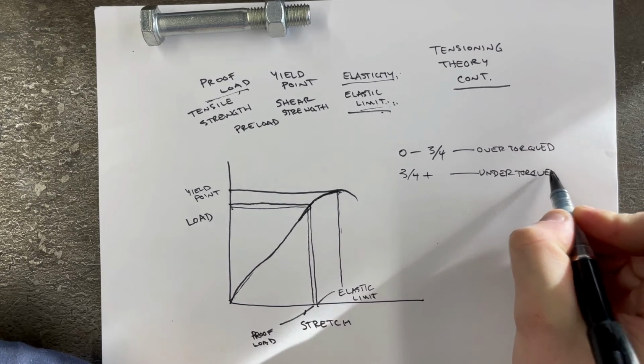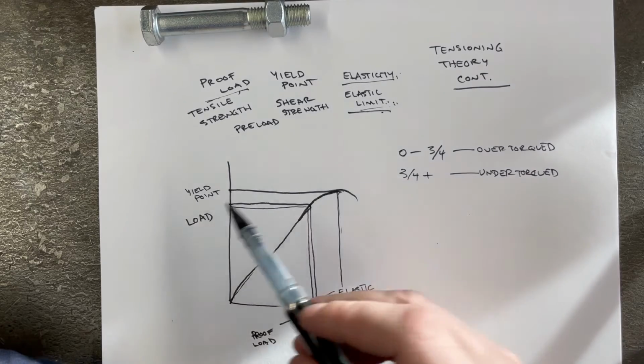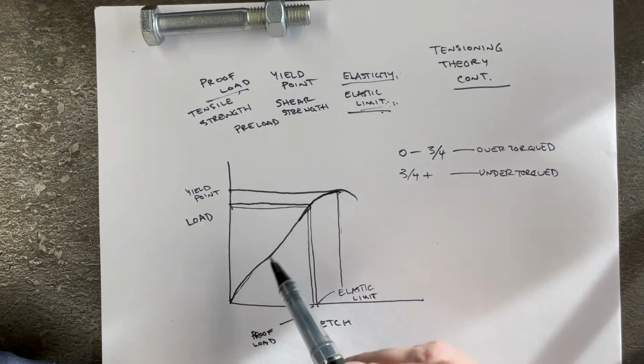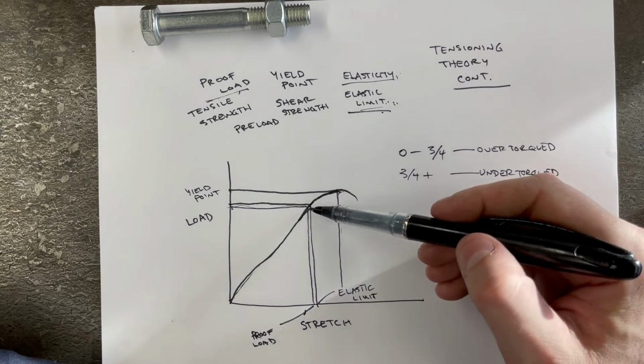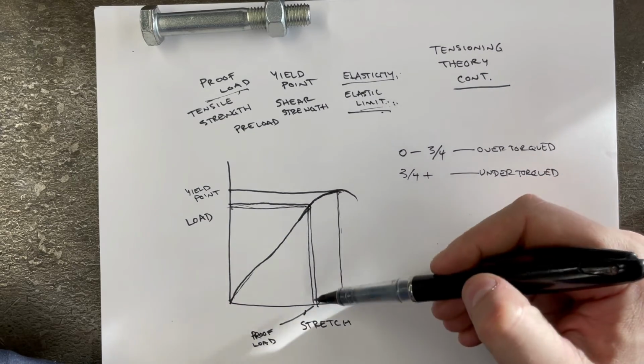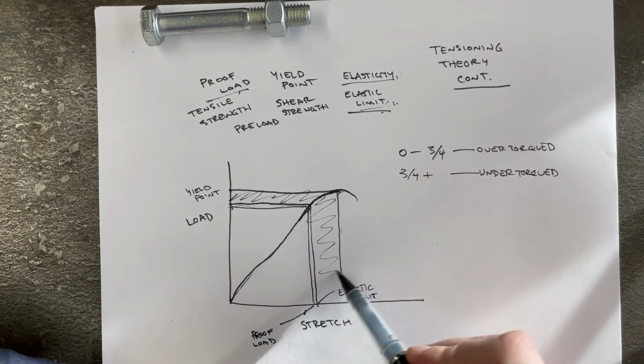So that's why, if you were just to do it by hand. So that's why it's really important when you're dealing with fasteners to keep in mind when you're dealing with small ones that you can really quickly and easily overstretch them and neck out a bolt and get inside of this zone that you want to stay out of.